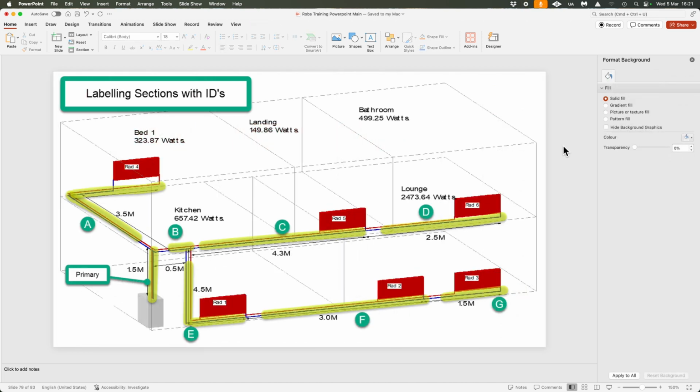Right, so we're now back at our next point here. I've completed all of the index circuit calculations, and the bits that I'd missed out were, so this section of pipework here was just 15 millimeter pipework, which gave us quite a high pressure loss because it was carrying both the energy for the bathroom and the landing. And then this one I dropped down in size, I think to 10 millimeter, just because it's taking the bathroom. You can try it with different sizes of pipework, and you can play around with it in your own house and stuff.